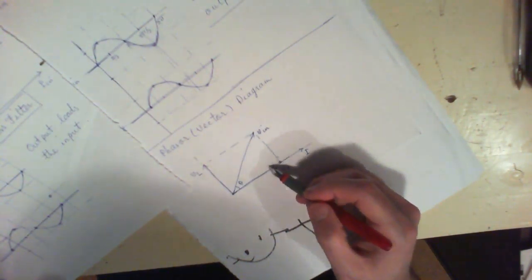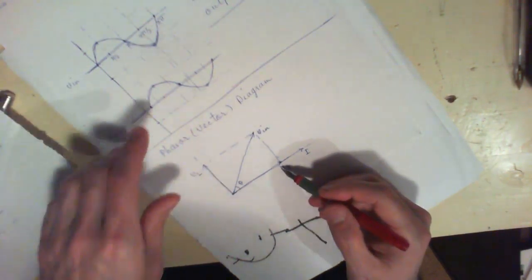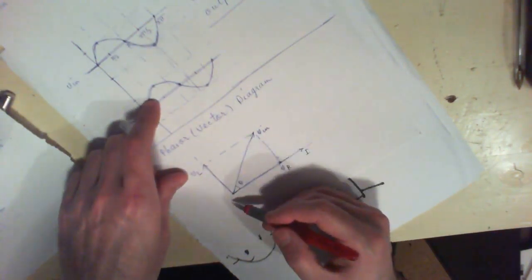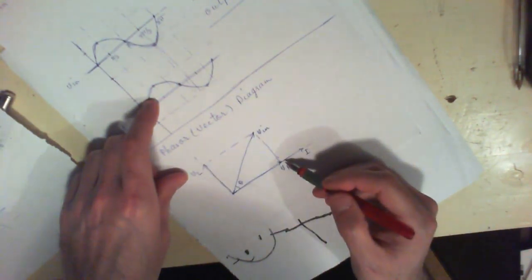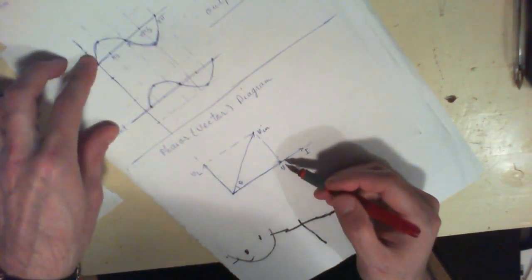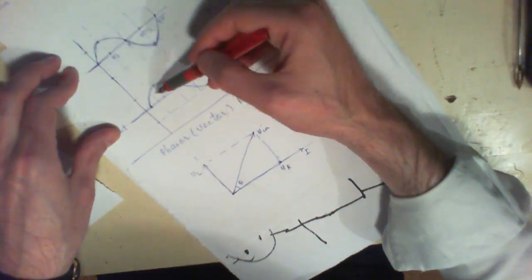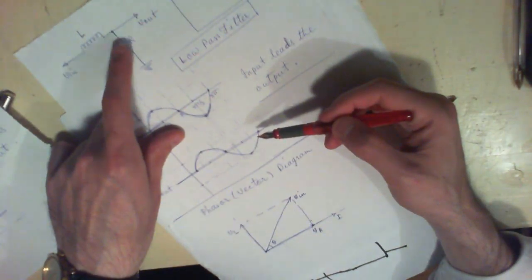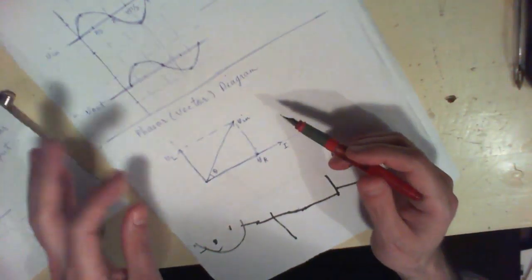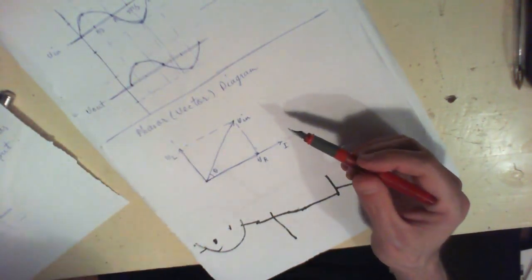And this part is the case where the output voltage is on your resistor, which is this case over here. In this case, you see that V of in leads the output voltage, and as you can see over here, your input voltage is leading the output voltage, and this is the voltage across the resistor here. So that's very simply your phasor diagram.